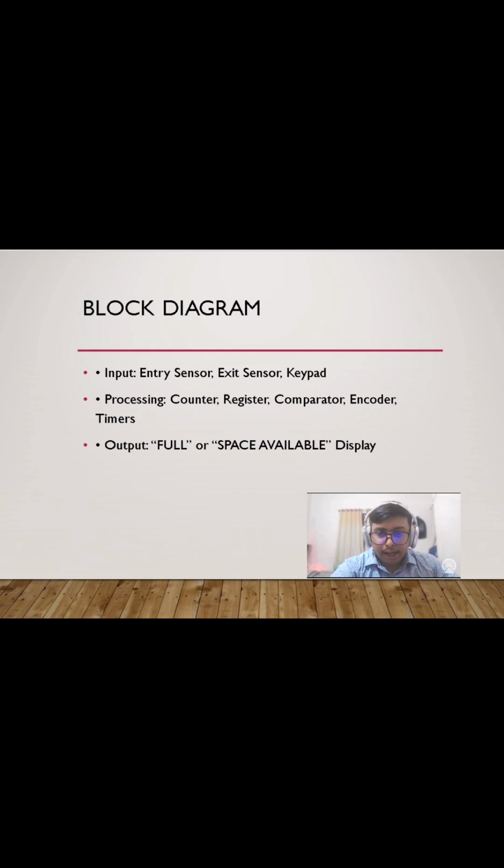And second one is fixing the duty cycle. The problem is it is hard coded at 64%, and the solution is to replace the 555 timer with a PWM enabled microcontroller. And third one is sensor error. The problem is noise causes miscounts. The solution is to add a Schmitt trigger for signal conditioning. The upgrade requires revising timing and equations for the FSM stage.